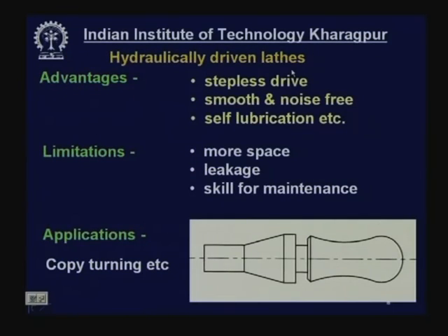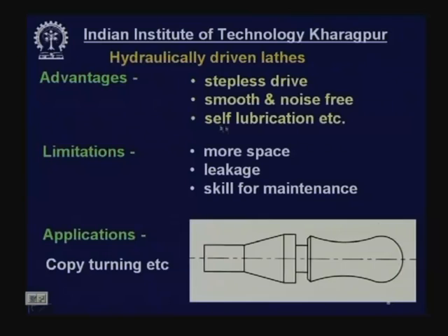Hydraulically driven lathes. Now, many machine tools are hydraulically driven. There are certain advantages or conveniences of hydraulic drive, like it gives a stepless drive. So, the speed and feed can be steplessly varied, operations are smooth and noise free, and self lubricating because of the continuous flow of the lubricant or hydraulic fluid.